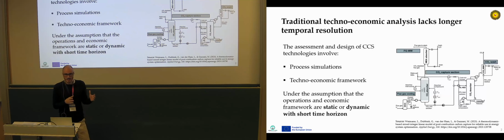So the assessment and the design of CCS technologies typically involves two steps. The first one is the process simulation, where you go into the details of the thermodynamics and the chemistry of the process. And the second one is the techno-economic framework, in which you take the KPIs, the parameters from the process simulation, and you try to assess the overall economic performance of the system.